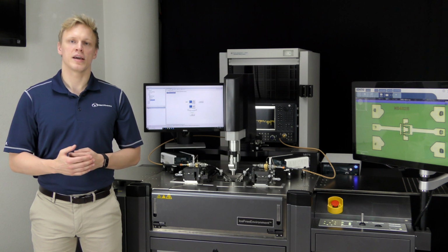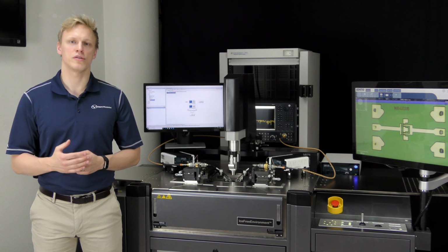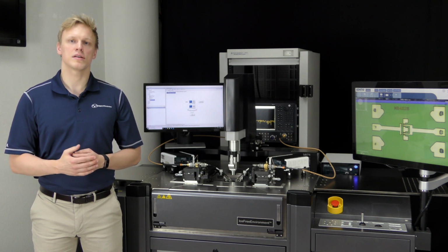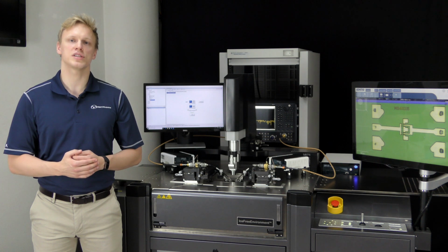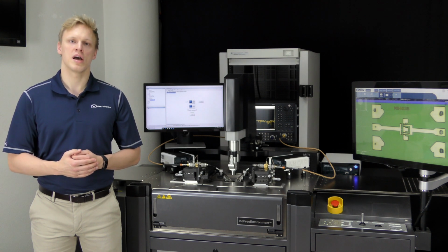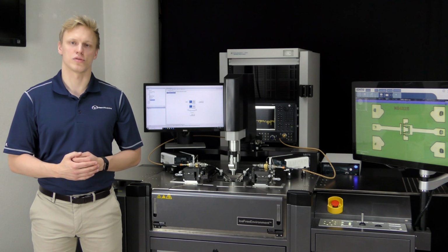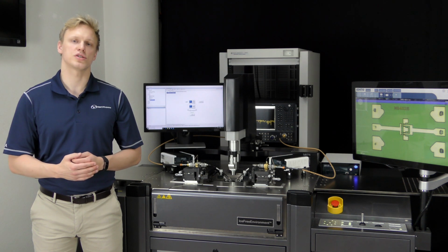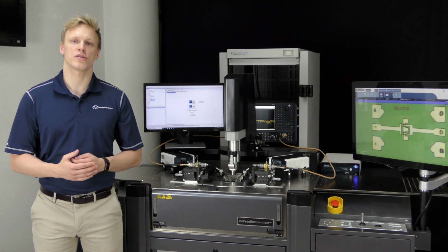In summary, pulsed AV measurements are a useful tool for characterizing or performing parametric analysis on a transistor. Pulsing the bias allows us to operate the DUT under quasi-isothermal and isodynamic operating conditions and explore the device performance in its breakdown region. Adding synchronized pulsed S-parameter measurements empowers us to extract more accurate compact transistor models. With Maury Microwave's synchronized pulsed IV solution and Keysight's PNAX, you can overcome all the limitations of DC IV measurements, characterize your transistor's true performance, and extract the most accurate compact transistor models at frequencies up to 67 GHz.